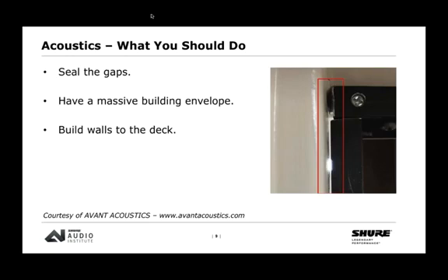Also, you must seal the gaps. So anywhere there can be air that moves through a gap, audio can move through there as well. So things like doors and windows and other penetrations, maybe where walls meet each other, the floor and the ceiling. If air can get through there, so can sound. So make sure all the gaps are sealed.